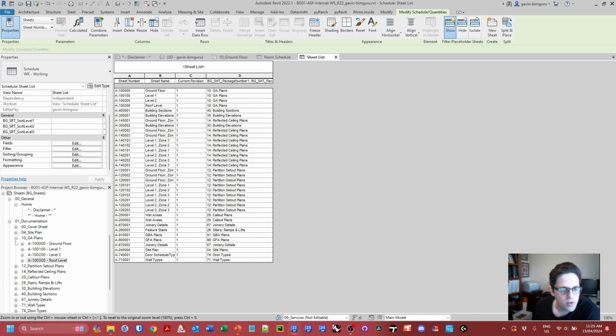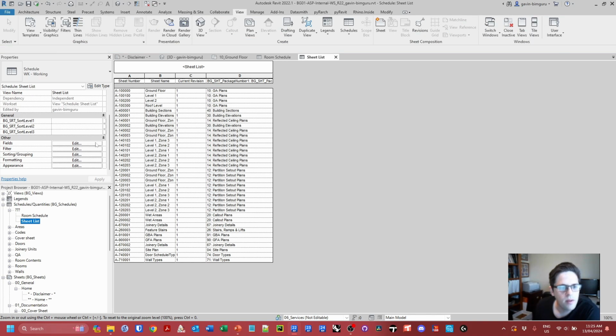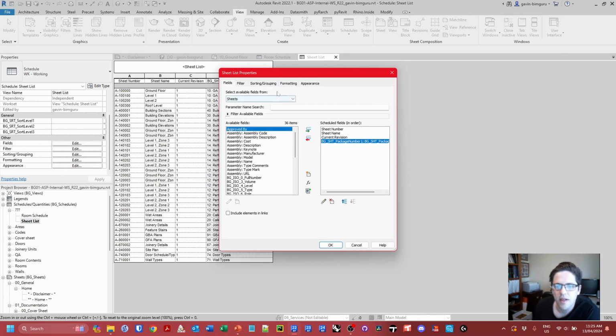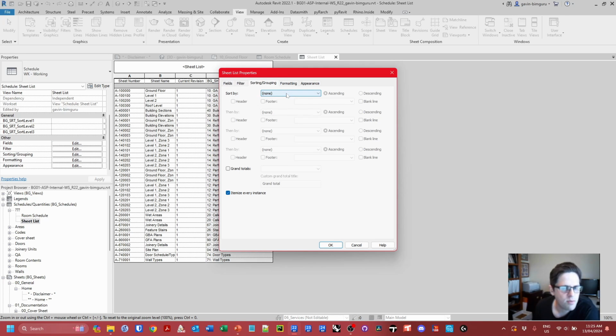So what I'm also going to want to do back in this schedule is probably put this as a header. Now I think, yeah, so that's one limitation with combined fields. You can't make them headers. There is a limitation there.